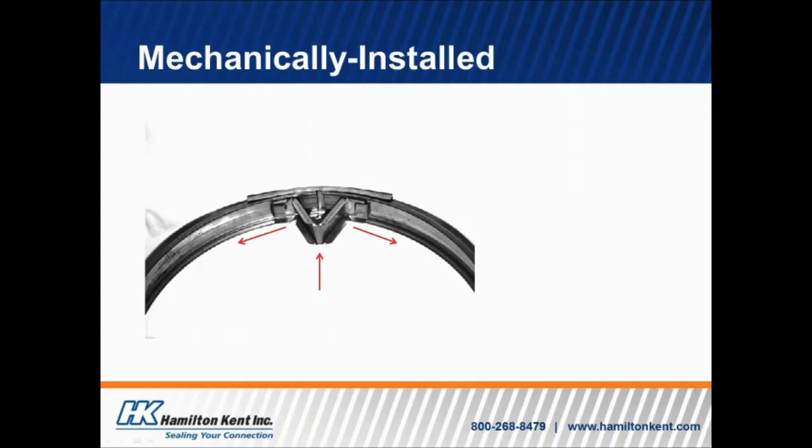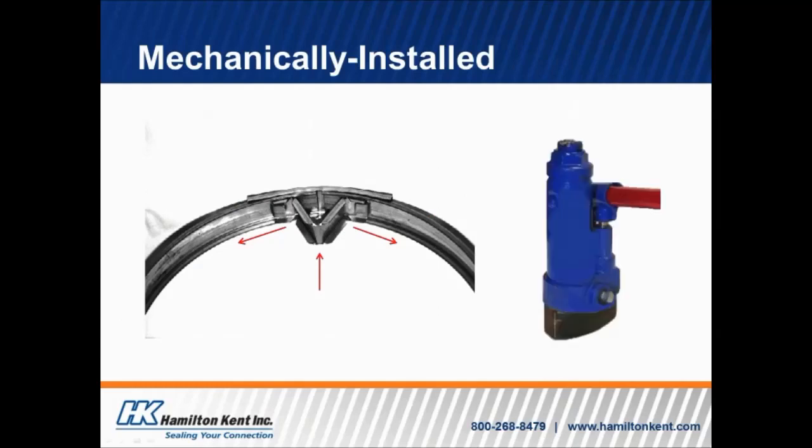Another type of connector we have requires a jack that actually sits in the bottom side of the hoop, and then you jack it into place, and you can see in this left-hand picture, it puts pressure going up into this V, and as that V starts to expand out as it's pressurized, it's going to be putting pressure to the right and to the left on the hoop to tighten it into place.